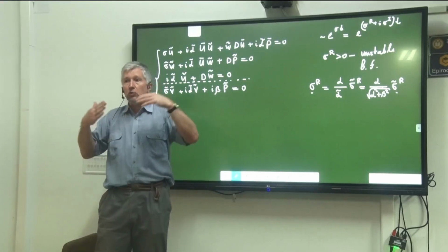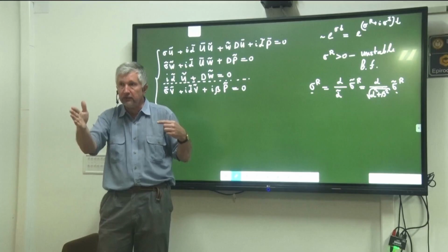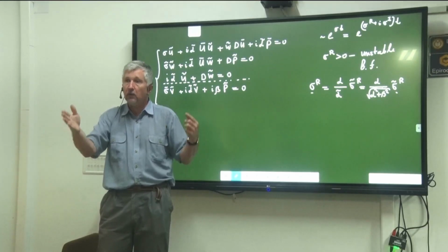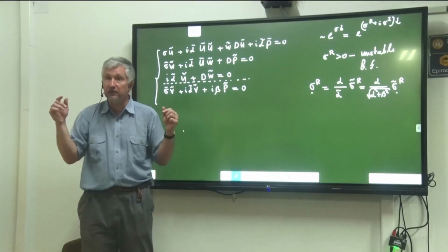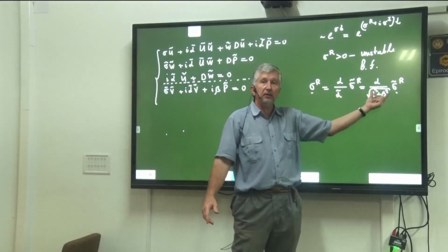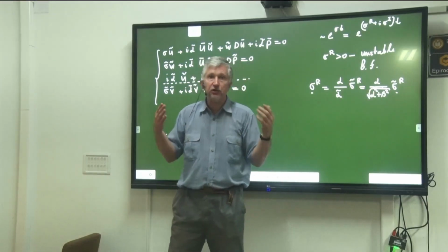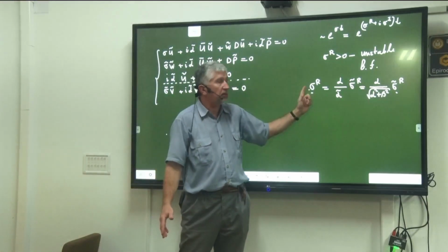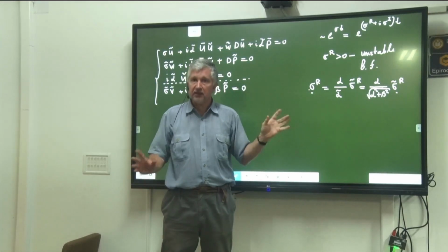Okay? And if we insist on considering the situation where the perturbations somehow propagate or exist in the direction perpendicular to the main flow direction, when beta is not equal to 0 and perturbation v is not equal to 0, then we conclude from here that the growth rate of these truly three-dimensional perturbations is going to be smaller. Is that clear?